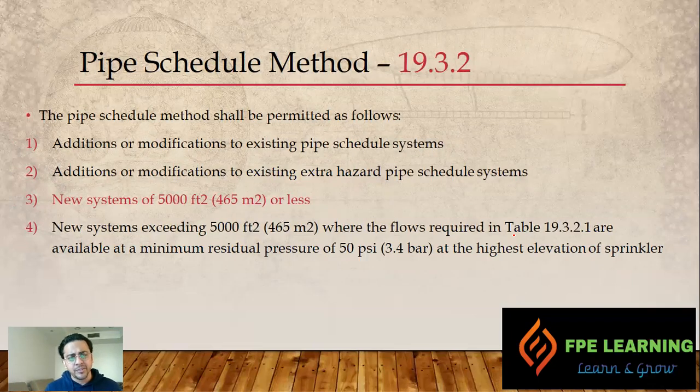The maximum capacity we have is 5,000 square feet. It's very small, right? If you see the hydraulic calculation system, the maximum system protection is up to almost 50,000 square feet, right? Around 48,000 or 52,000 square feet. And this is just 10% of that. So the area is very limited, something around 25 meters by 20 meters, that's it. So we have the area limitation.